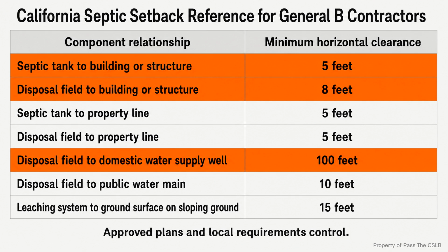This is also a documentation issue. When old infrastructure appears unexpectedly, the contractor should record the condition, notify the responsible parties, obtain direction from the authority and qualified contractor, and protect the schedule from undocumented extra work.